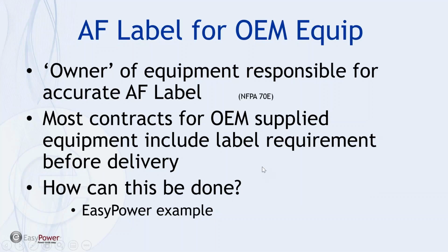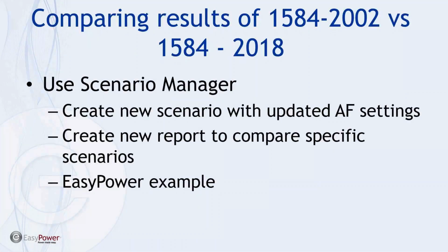So we're getting down to probably the biggest subject that people have an interest in, and that is comparing the results of IEEE 1584 old standard versus new standard. I'm going to do this with the scenario manager, and the steps involved are: create a new scenario with the updated standard as part of the analysis, and create a new report form to compare specific scenarios. To do this, I'm going to use the same example that we've been working with.